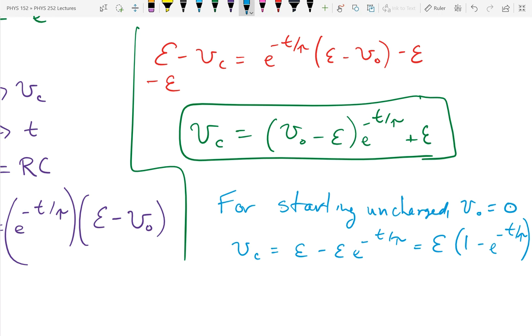That's the equation that we had in class yesterday that was just given on faith. That the voltage is EMF times 1 minus E to the minus T over tau. It starts with a voltage of 0, and then it's going to build up. Notice the E to the minus T over tau, when time is 0, that's 1. So I have the EMF times 0 at time equals 0. And then that second term is asymptotically approaching 0. So that means that my voltage is asymptotically going to be approaching the EMF.